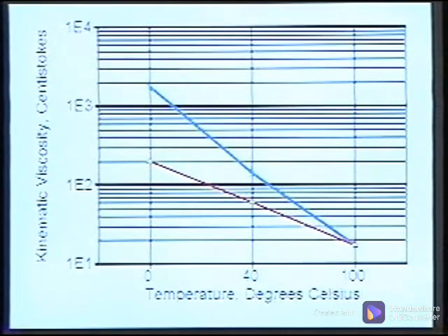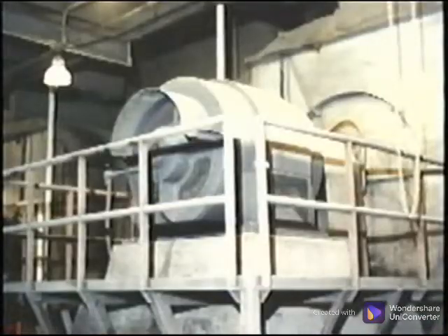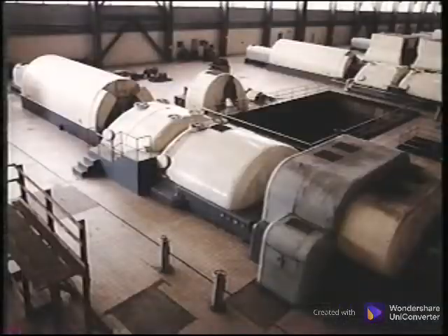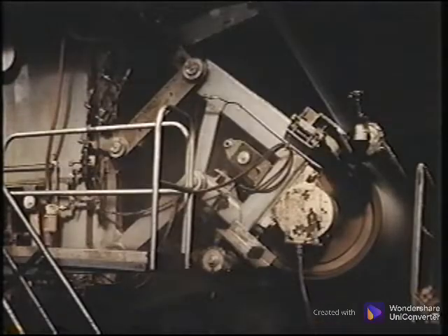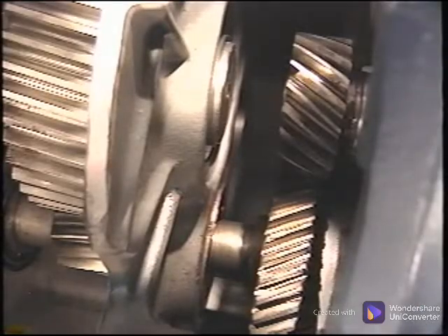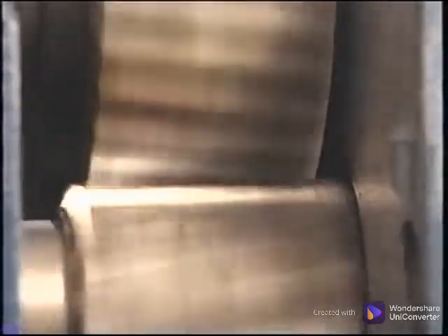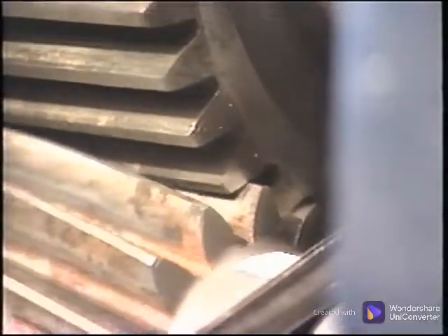When the viscosity at 40 degrees centigrade and 100 degrees centigrade is plotted on a special scale, then the viscosity at any temperature can be calculated and then compared to the sample to determine whether it is the correct lube for the machine. Each machine has characteristics that demand a particular lube viscosity for optimum performance. High-speed machinery must use a low viscosity or lightweight oil, while the lube of slow-speed machinery should be higher viscosity or heavier. Since the lube should provide a film between internal components, heavier loads such as gearboxes require a heavier